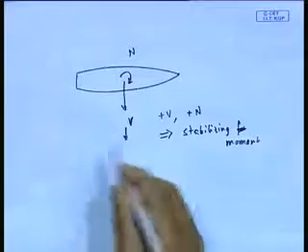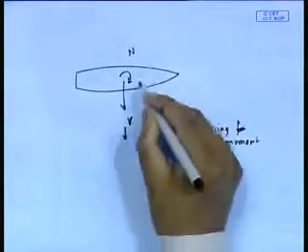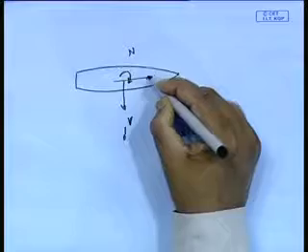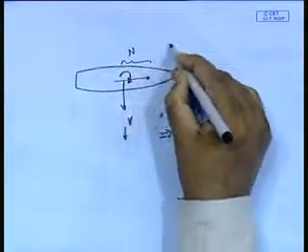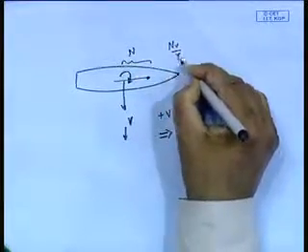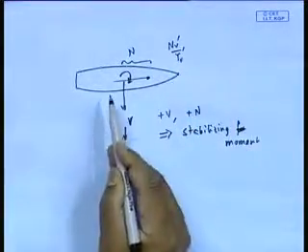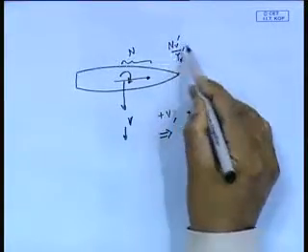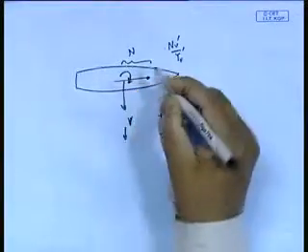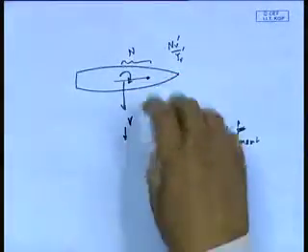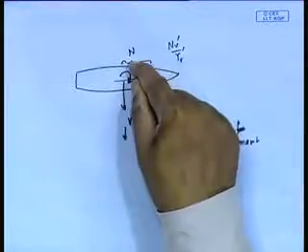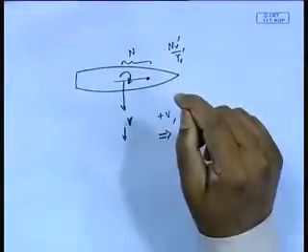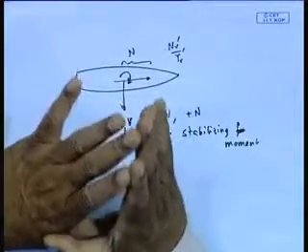Why? Because remember that we have always said that the center point here, this point P, is given by this distance N v by Y v, and as it moves backwards, it becomes more and more stabilizing. Now, N v is always negative, so this was taken as negative. So, it becomes more and more positive, it becomes stabilizing. Essentially what it means is that if N was supposed to be positive with v positive or less negative, that means it is trying to turn this side, and I can end up getting a positive stabilizing moment.